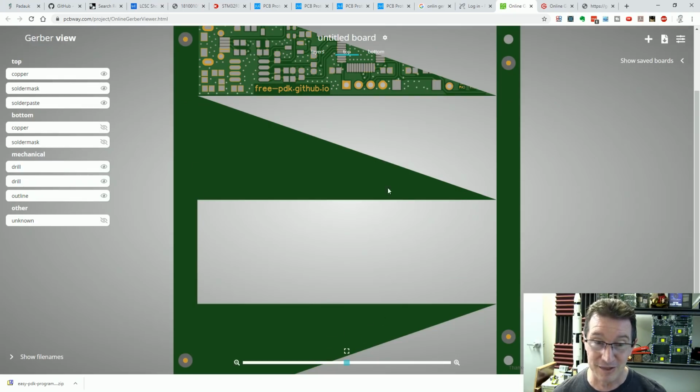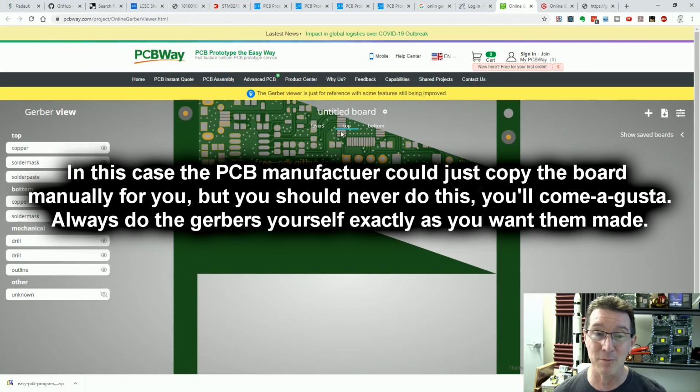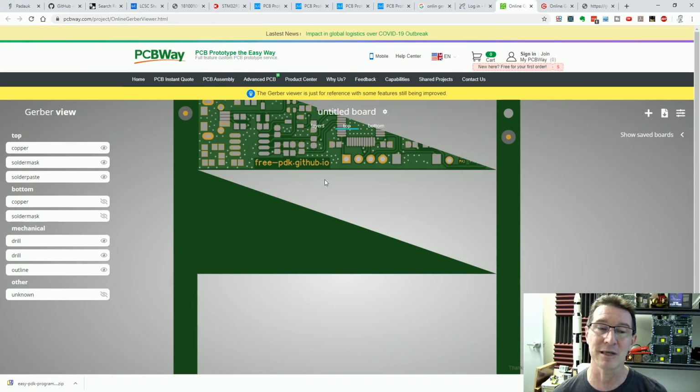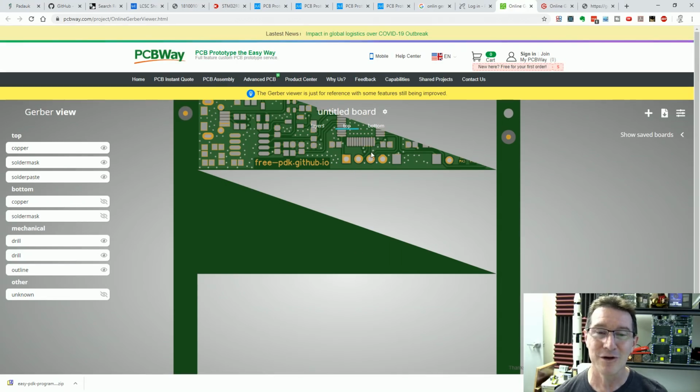So the data is physically not in the Gerber file for these other boards. It's supposed to be 1, 2, 3, 4, but there's only one board there. So that hasn't been rendered from EasyEDA or whatever package they use to do this in. It just hasn't been done. They haven't produced those Gerbers right. So that's useless. So you don't want to get that manufactured. This is why, don't touch manufacturing panels like this if you're just making your one-off board. It's more hassle than it's worth.